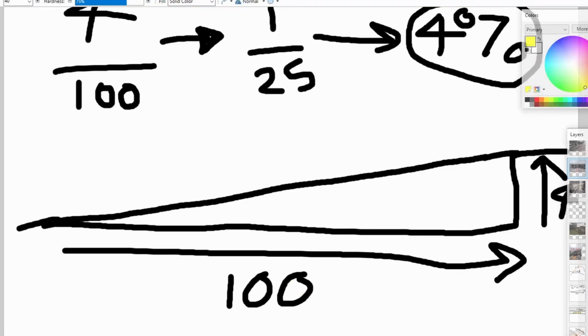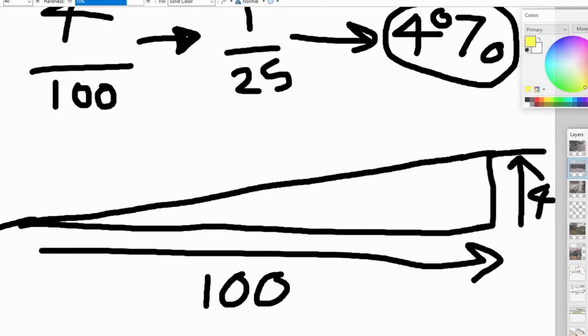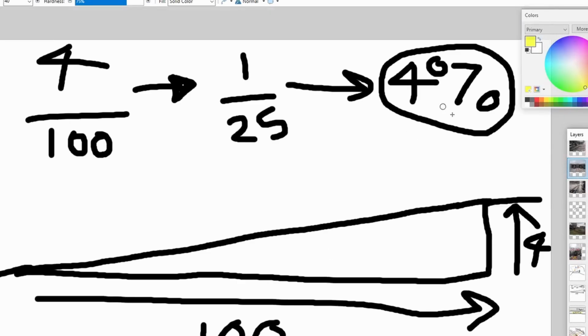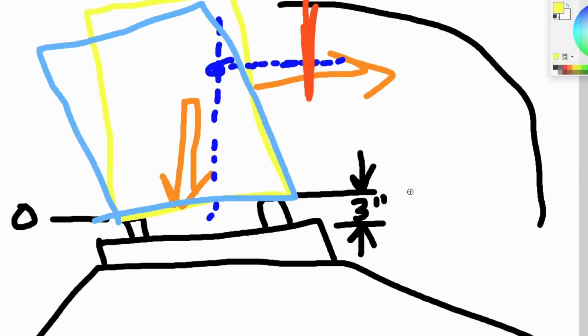We also have grades. The railroad needs to run up hills, so we have grades that allow the trains to go up and down, measured in percent if you're in the States, or in a ratio if you're in other parts of the world. We also have other ways to measure what the track can do. We have superelevation, where we can raise one rail or the other to allow us to move faster through the same geometry, because we can lean the center of mass of the train into the force that's trying to fling it off of the tracks.